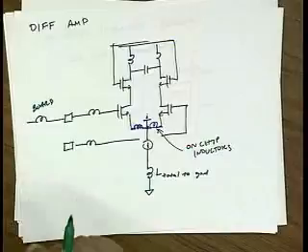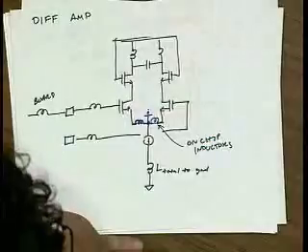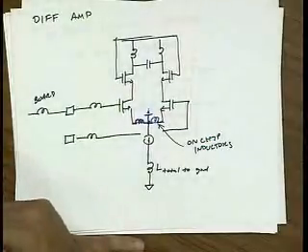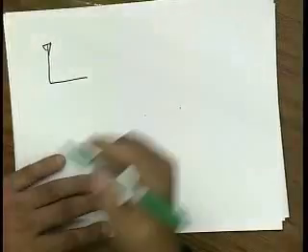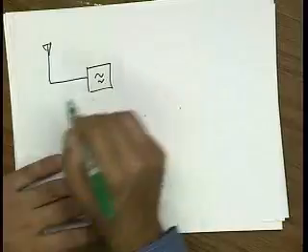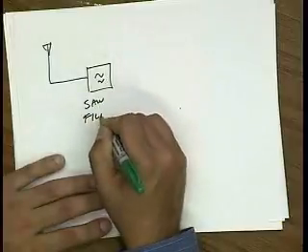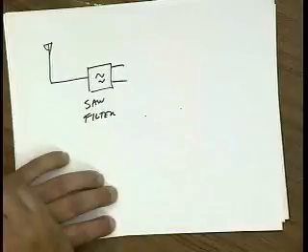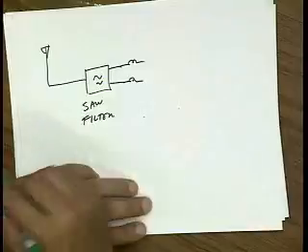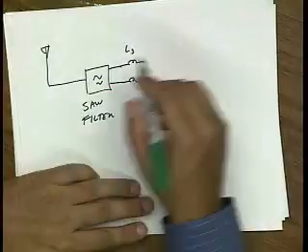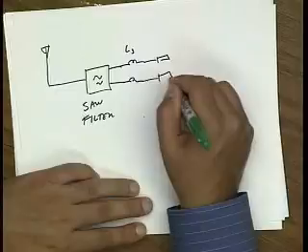Okay. Now you may say, well, this is differential. Isn't that a problem? A few years ago this was a problem, but nowadays it's actually fairly common to find filters that are differential. So if you're building a system, your antenna is usually single-ended, okay? Although that's not necessarily a requirement. You go through a filter. This is a SAW filter, and its output is differential. So you're in business. Then you put in these gate inductances externally to get the match, and then you go differential on chip.